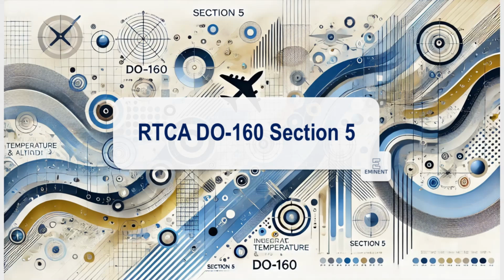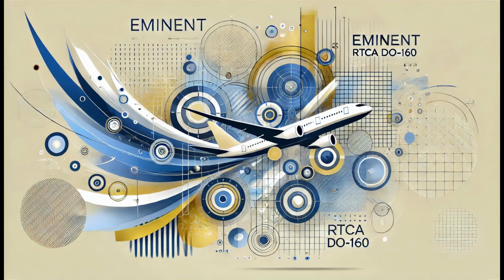Category T. Category T tests focus on equipment exposed to both high humidity and temperature variations, as found in certain unpressurized areas of the aircraft. Failures commonly include moisture condensation on circuit boards, which can lead to corrosion or short circuits. Mitigation: conformal coatings on electronics and moisture-resistant seals help prevent condensation and protect internal components.